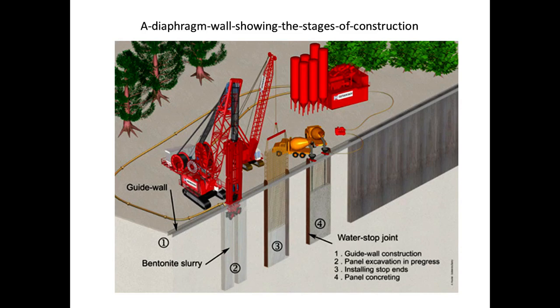On very large scale heavy-duty civil engineering, where you have to make a retaining wall, we use what's known as a diaphragm wall. So here, instead of just pouring columns into casting a series of piles, if you like, into the ground, we're casting huge slabs of reinforced concrete in sections into the wall.